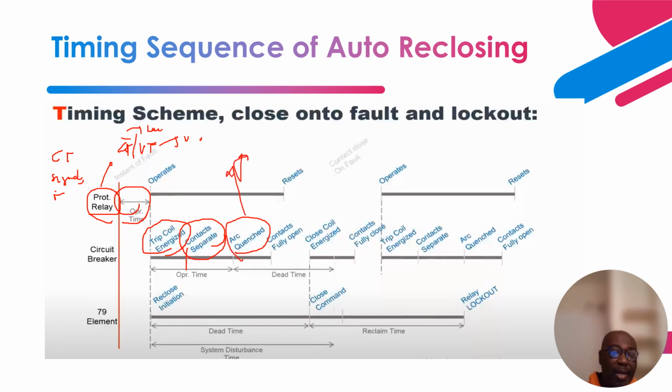That is when either the vacuum or SF6 comes into play, as a quenching medium to mitigate any restrike based on the voltage that is developed across the contacts. Whilst the contacts are trying to separate, the arc develops, and that arc needs to be extinguished until the time that the contacts fully open.